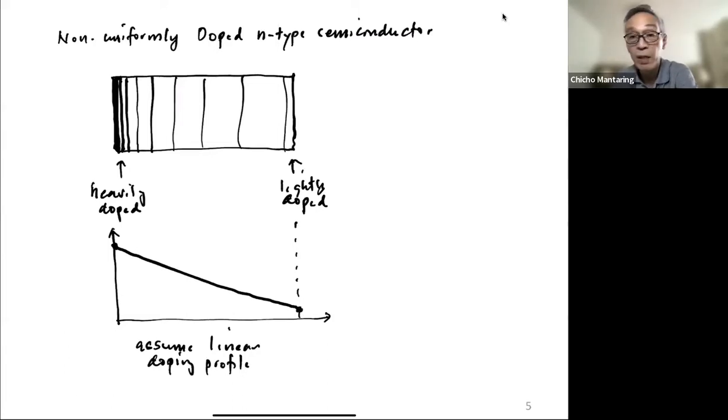Okay. So if my semiconductor is completely ionized, and I described what complete ionization was last time, that is, if this is N-type, completely ionized means all of the donor atoms will have electrons that are promoted to the conduction band.